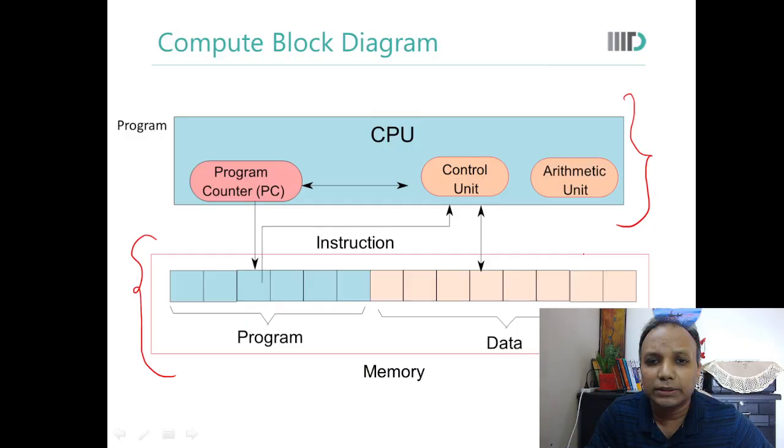Now, what does this CPU have? CPU will primarily have an ALU or arithmetic and logic unit, which is used for doing all mathematical and logic operations. Basically the capabilities of this ALU will define the ISA. For example, if the arithmetic and logic unit can handle floating point operations, then the ISA will reflect that. If it can't, then your ISA should not have floating point operations.